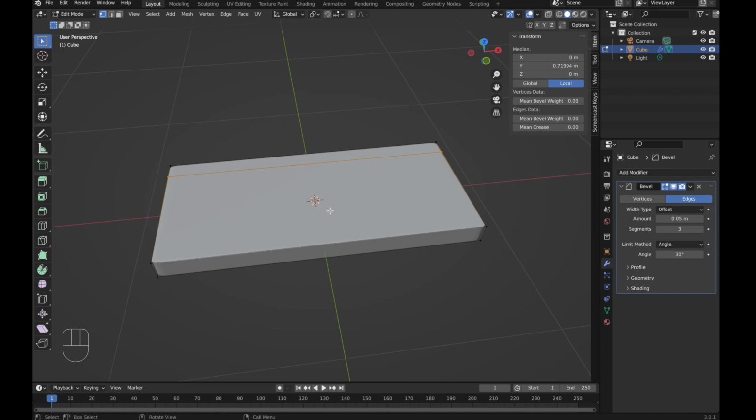Similarly, Ctrl+R executes a loop cut in the Y-axis direction. If a yellow line appears, right-click to cancel the movement and cut in the middle. Since we want to raise both sides of the base, expand the cross-section we just entered with Ctrl+B bevel to the side.